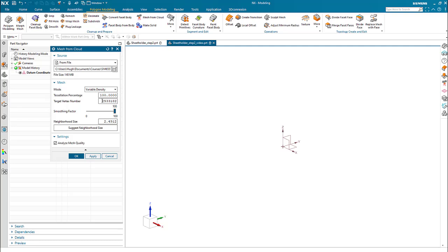And you saw that warning that if I'm over 500,000 points, then the system's going to lag. So let's take that to heart and put it down to 400,000. I think the default is keep all the points, so don't do that after you receive that warning.